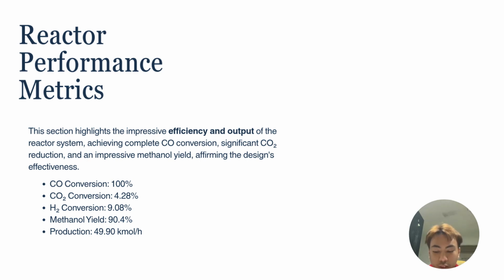So the carbon monoxide conversion is 100%, which is complete conversion. Carbon dioxide conversion is 4.28%. Hydrogen conversion is 9.08%. Methanol yield is 90.4%, and the production is 49.9 kilomole per hour.